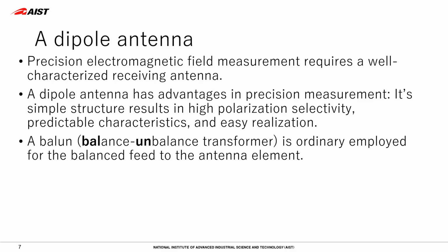With the development of telecommunication and electronic devices, the requirements of the electromagnetic field measurements are getting difficult. To carry out a reliable measurement, the receiving antenna characteristics are pretty important. Ordinary antennas you may use in daily measurement are broadband antennas, such as a biconical and log-periodic dipole array antenna, to cover a wide frequency range of the measurement by a single antenna.